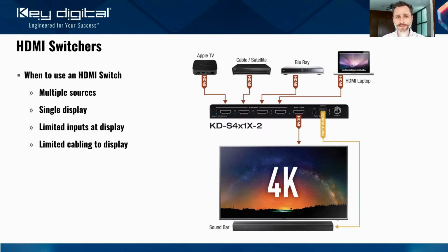So for those of you who don't know and may not have familiarity with HDMI switches, when are you going to use an HDMI switch? Well, you use an HDMI switcher to select between multiple sources to go to a single display. Now, that may sound pretty simple and straightforward to you. You say, oh, my HDMI LED monitor or display has 2, 3, 4 HDMI inputs. Why do I need to spend extra money on a switch?